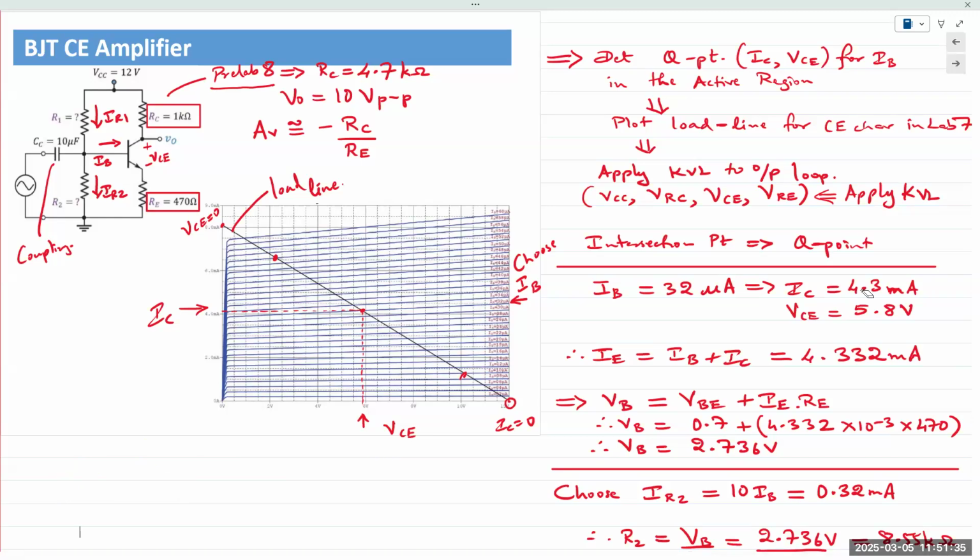You can use sweep, and it may or may not work. I don't know, I haven't tried it yet. But with manual data collection, you would obtain something like this. Then you plot the load line on it, find the intersection point. For every value of IB, you would have a corresponding value for IC. So if we take a point for IB like this one right here, we extend it to the left, that gives me the value for IC. IC divided by IB gives me the beta.